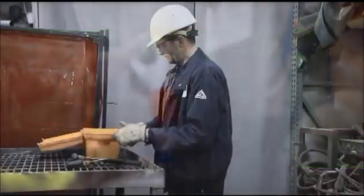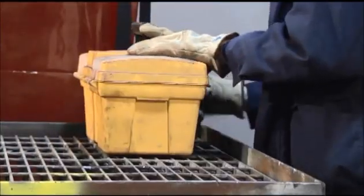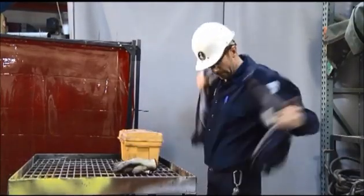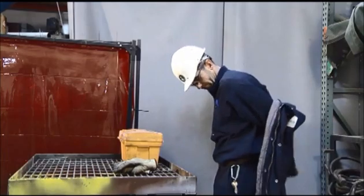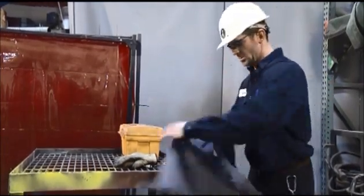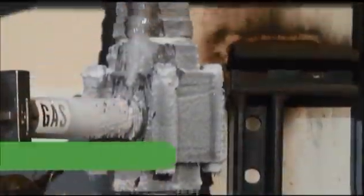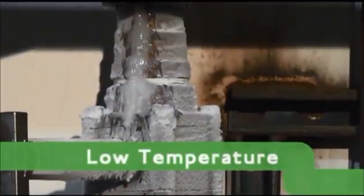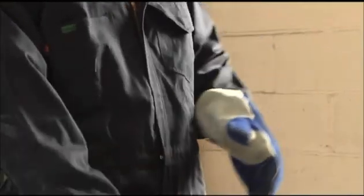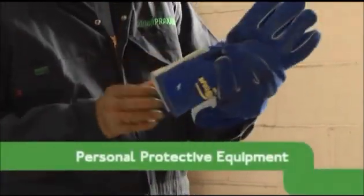Even after leaving an oxygen-enriched atmosphere, your clothing can still remain saturated with oxygen and present a fire hazard. That's why it's important to avoid any sources of ignition and immediately remove your work clothing after exposure to an oxygen-enriched environment. When working with oxygen in liquid or gaseous form, you'll need protection from the cold and pressure by wearing the appropriate personal protective equipment.